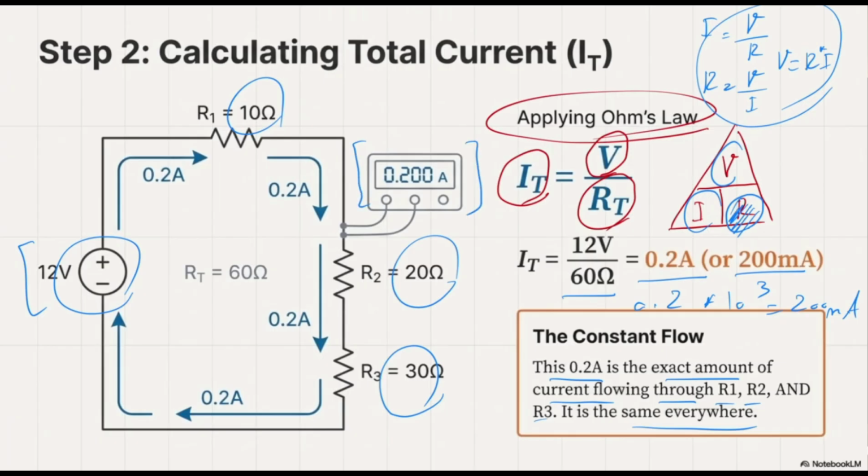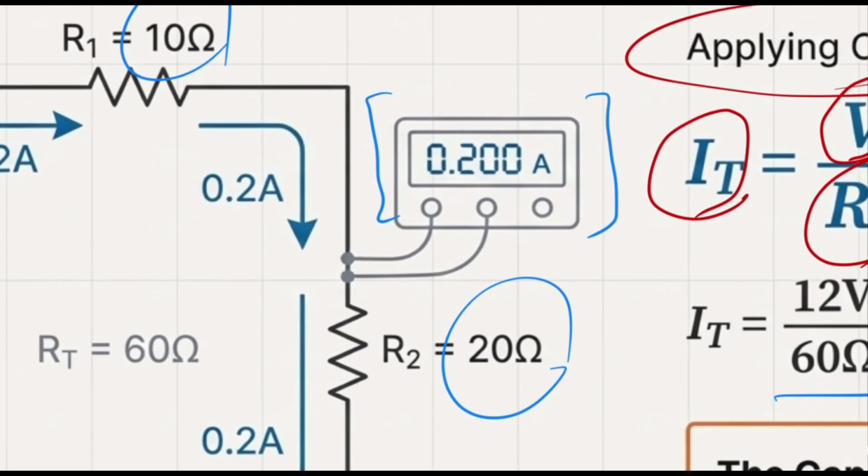One thing that we do have in order to measure the amount of current is something we call a multimeter, or to be specific, an ammeter. As you can see over here, an ammeter is connected in series. If we look closely at what is happening over here, I do have my current that goes through here. Then I connect my ammeter using 2 wires, the positive side of the ammeter and the negative side. By the way, we do have a lab and I'm going to talk about how you can connect it, but just keep it in mind.